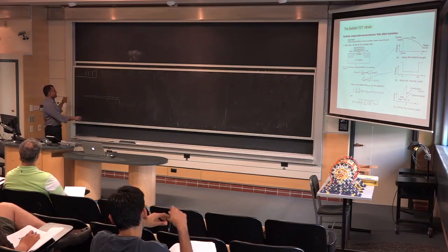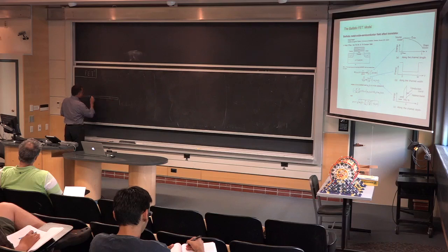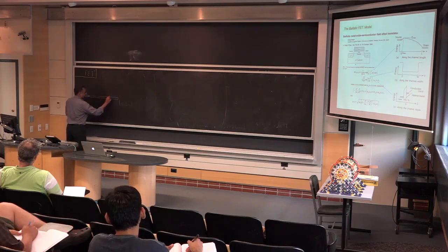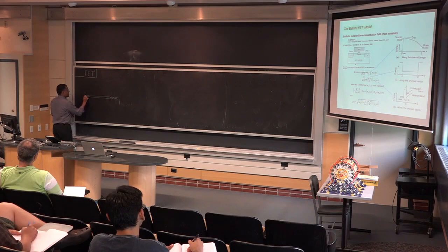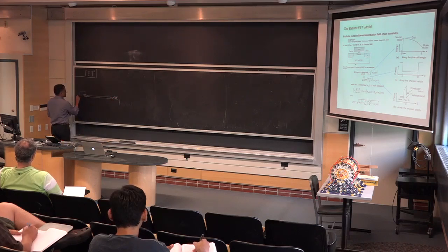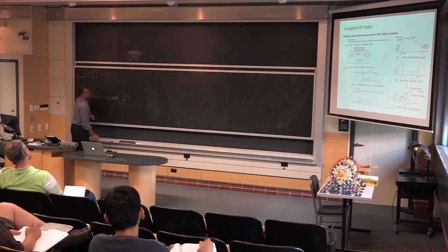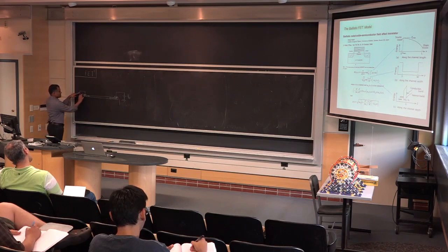After we took this two-dimensional semiconductor, we had two regions which were heavily doped. We imagine these are heavily doped, and then there are contacts made to the two regions, which are source and drain. We have, for example, grounded the source, and we are going to apply a certain voltage on the drain, which we are calling V sub ds, drain with respect to the source.